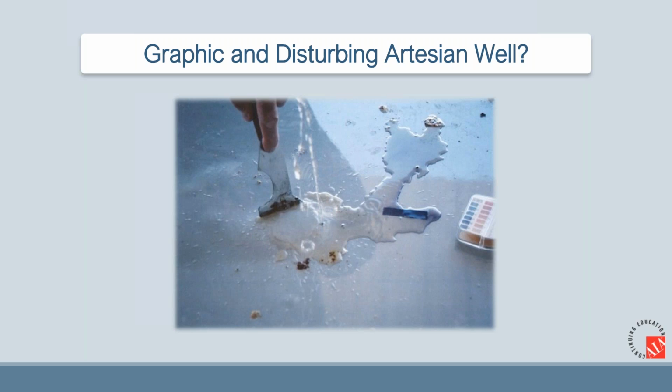So where did all the water come from? Well, unfortunately, underneath that pan deck was a laundry room. The laundry room was generating high moisture and steam. It worked its way up through the flutes in the pan deck, and managed to saturate the concrete, eventually coming into contact with the epoxy coating, condensing into a liquid, causing a separation. So again, changing the way we think about our designing helps us prevent these from ever happening again.